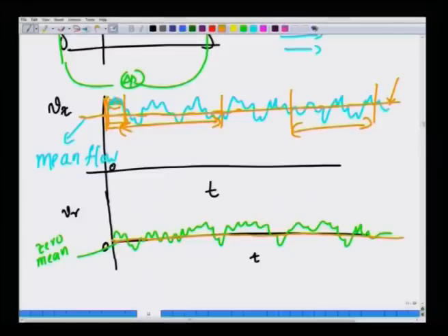The pressure drop is over the entire length of the pipe, and so there is a large amount of averaging going on when you find the relation between pressure drop versus flow rate in the turbulent flow regime. And so clearly we are not interested in knowing the detailed spatiotemporal variation of the velocity, for example Vz with respect to r, z and time.